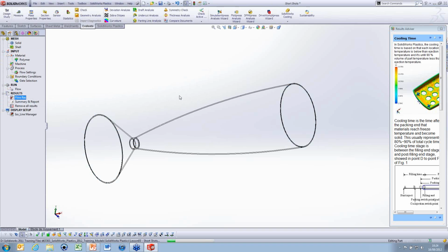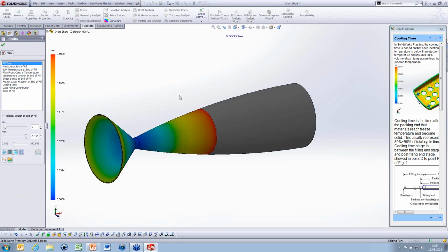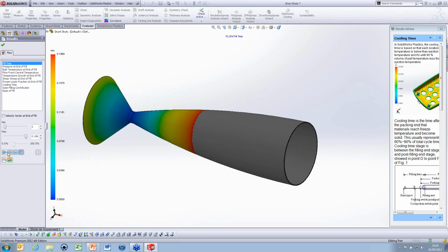If we read the pre-run results that I've got here, what we can see is that we actually get what's called a short shot occurring. So the maximum pressure of the machine has been reached, but the mould hasn't completely filled. And this can occur when you have very thin-walled components, just because you require a higher pressure to completely fill the mould.